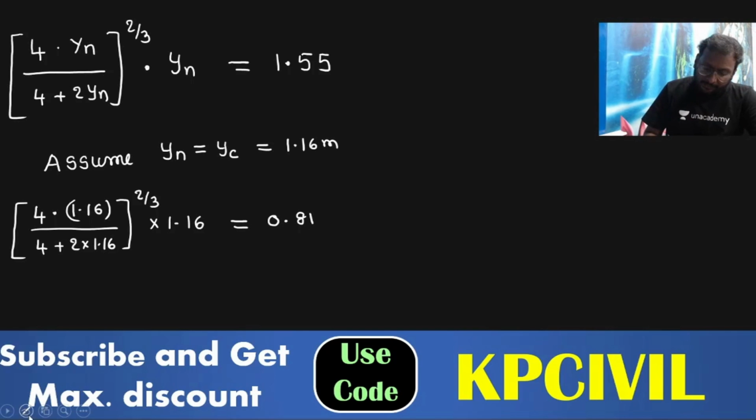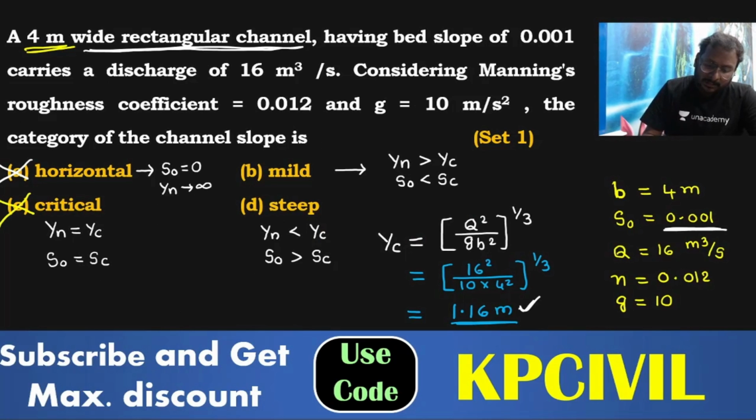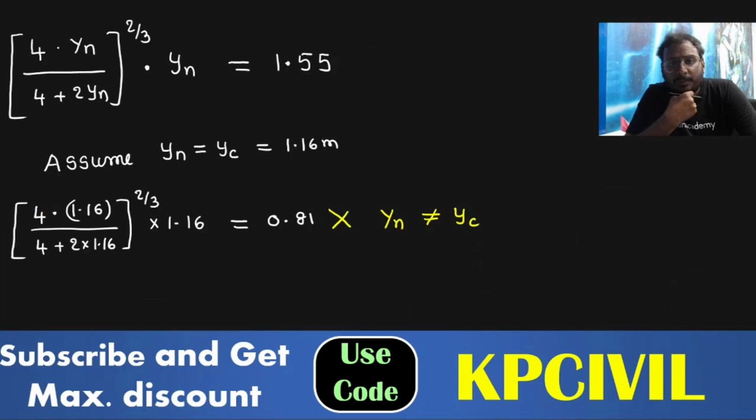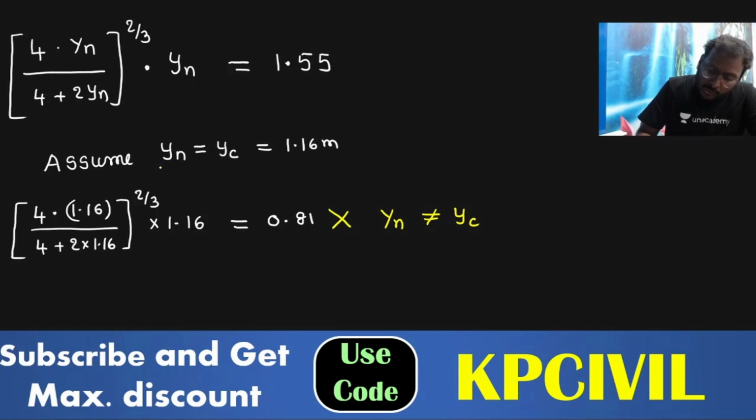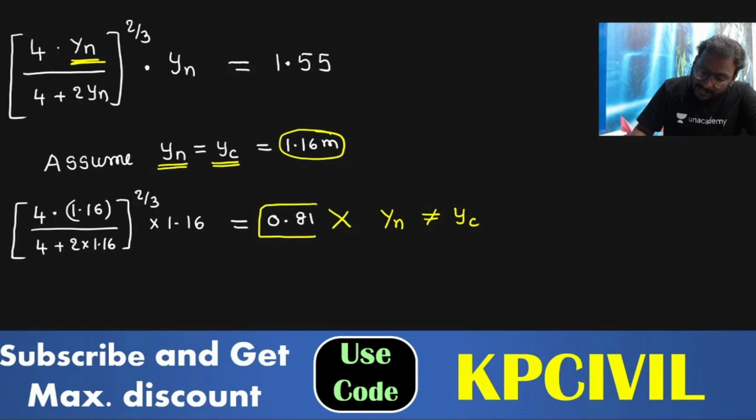It is not 1.55, na? It is wrong. So yn is not equal to yc. Since yn is not equal to yc, the critical slope condition is cancelled. Got the point? You are assuming yn is equal to yc, and in place of yn you are substituting 1.16 meter. If you substitute, you get 0.81, but you need to get 1.55.